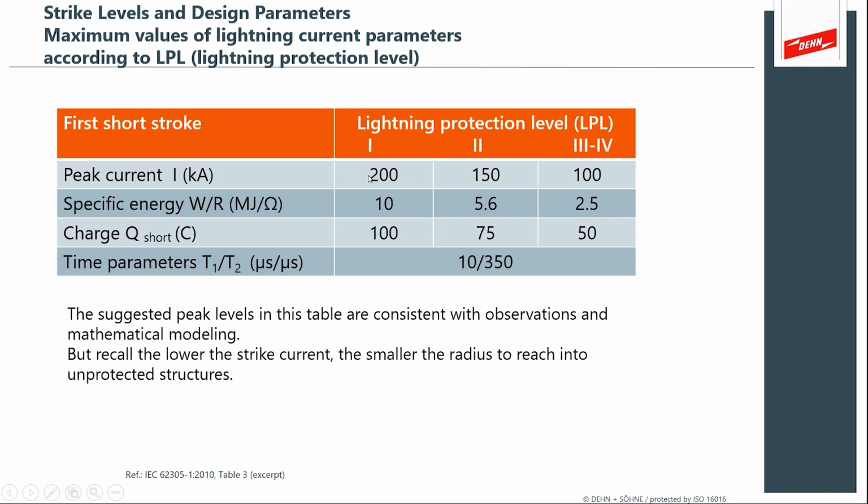And that's what you see in the standards, is that if you can accept more risk, you're willing to have essentially less lightning current. So that's how this standard in this chart shows. What's important is that you have levels of lightning protection that are less robust than the LPL1, which might be the most controlled of risk.